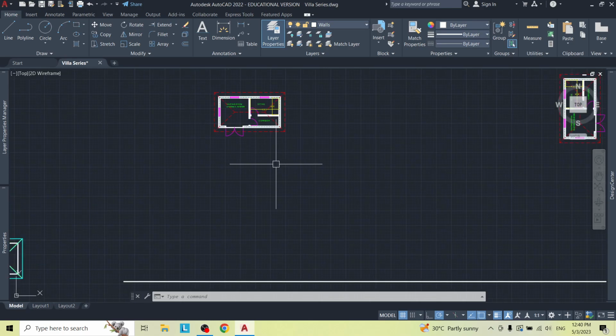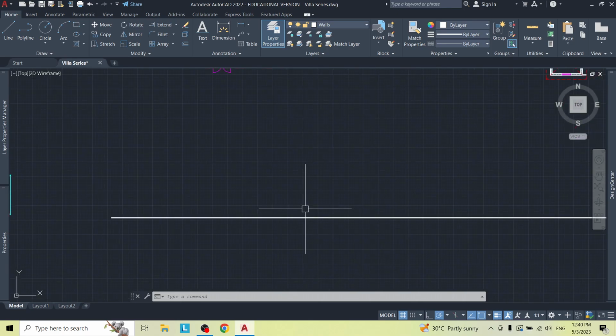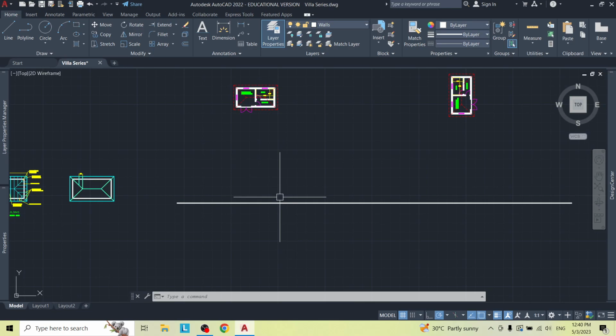All right. So what we want to do is establish our heights. This is an easy way. It's going to help us immensely in doing our elevation drawing. So learn this. If you're not familiar with the elevation drawing, learn this method. So this is my baseline. This is going to be like the ground line of the outside of the house, the dirt.